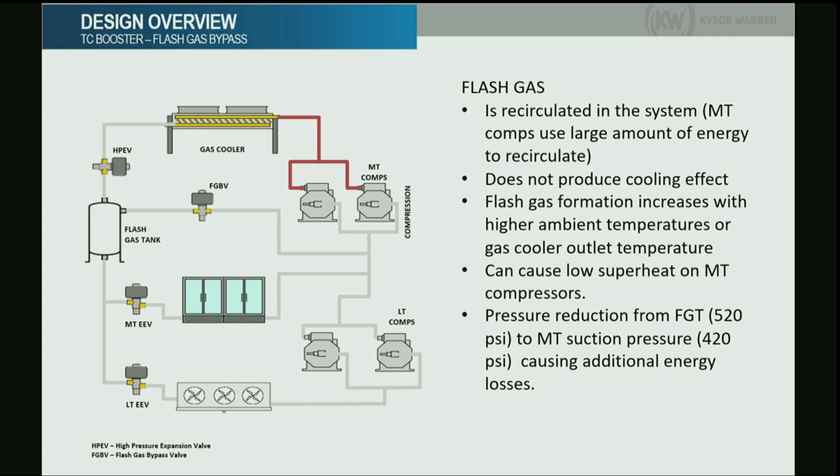So here at the inlet of the gas cooler, we have a high pressure and temperature CO2 going into the gas cooler. Now, I mentioned before, it's a gas cooler and condenser. Well, if your ambient temperature is above 87 degrees, 85 degrees, most likely you will be in transcritical mode and you will not be condensing CO2. Above the 87 degrees and 1,000 pounds, the CO2 will not condense. That means it will not change phase from vapor to liquid.